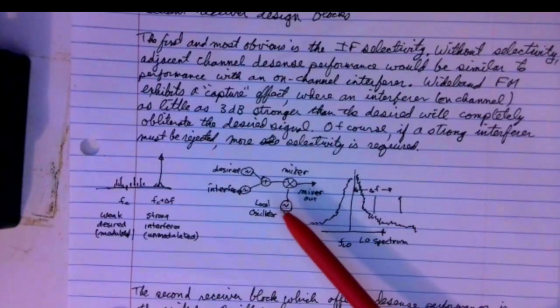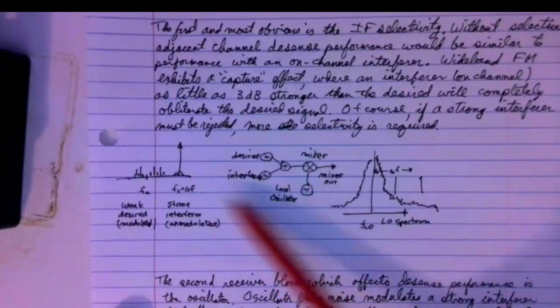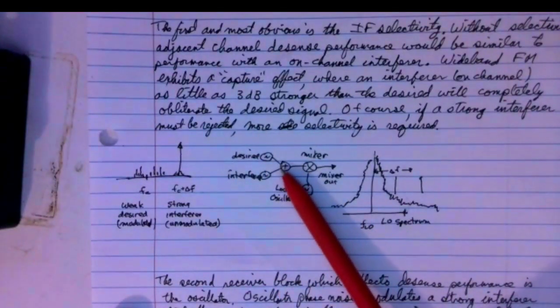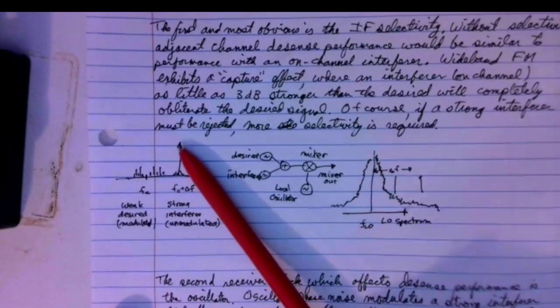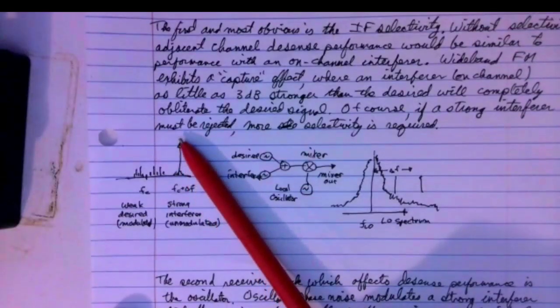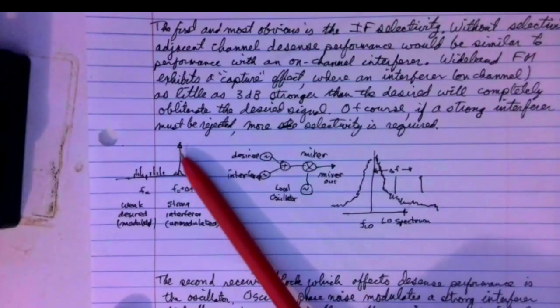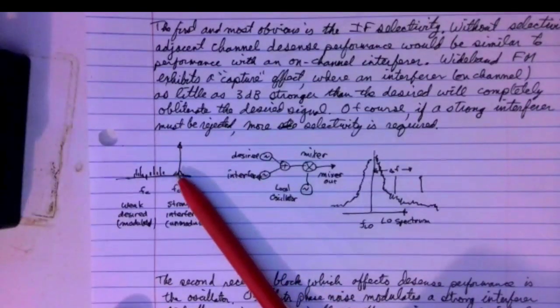And so let's look at some of these signals in the frequency domain. All right, so this right here, our interferer is a tone. So that looks like a spike in the frequency domain. And it may have some phase noise on it, ideally not too much, but every source has some phase noise on it. But we're going to ignore that for the purposes of this analysis, and so we have a good signal generator. So it's strong. It's a strong signal, and it's unmodulated, or at least not intentionally modulated.